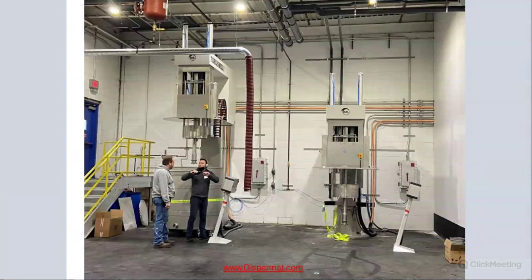But if you are using a machine for many different products, then maybe this solution is not the best one, because you want to be able to replace the baskets quickly to move in between color families. So with the TM, this basket would be fixed and you can't easily take it off. There's no quick change system. So really only think of using this system for your biggest movers and product and your materials you don't change often. So that would be a perfect solution.